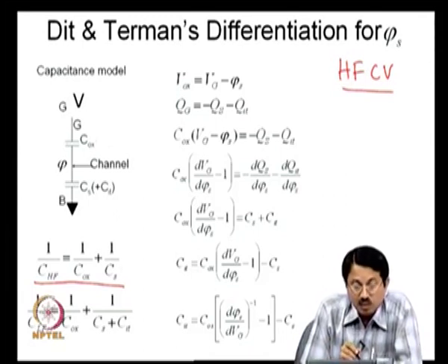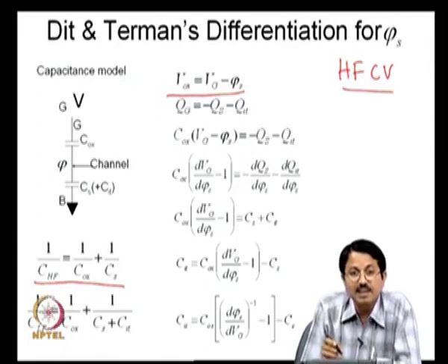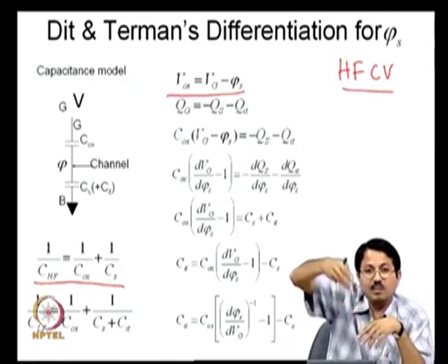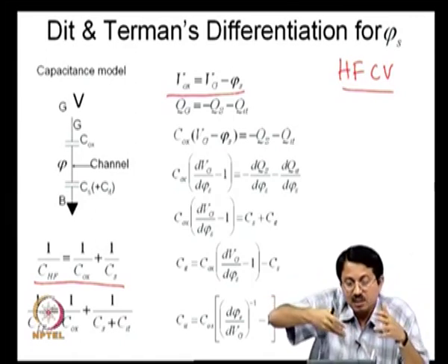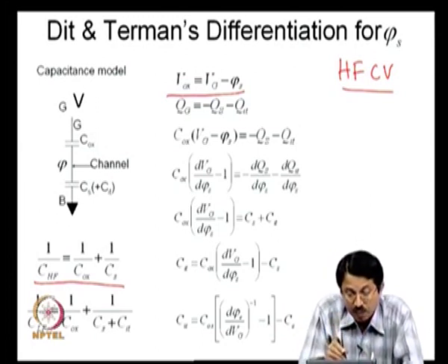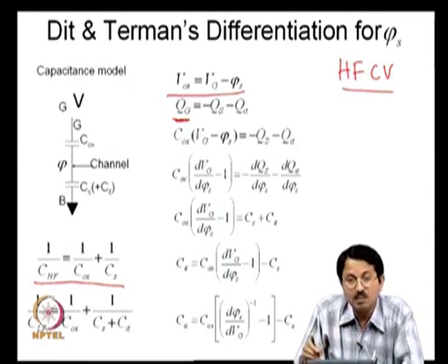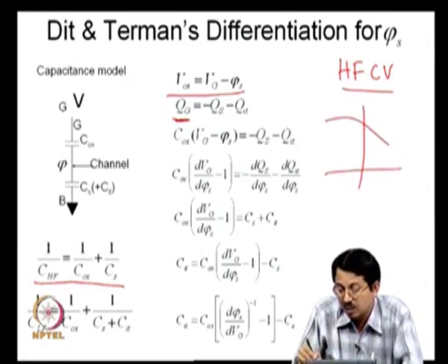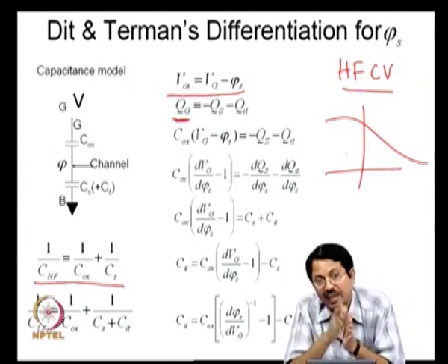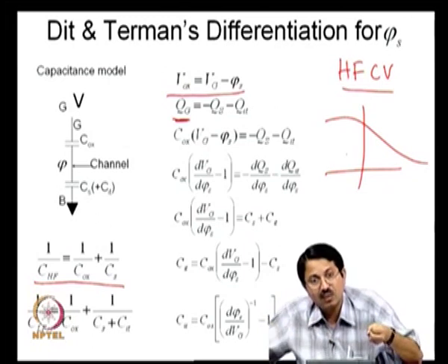Okay. So, let us look at this, right. Your oxide voltage can be written as Vg minus psi s, right, and that is what it is. Vox is equal to Vg minus psi s. Okay. Psi s is a silicon potential. Now, there are two elements in series, total voltage is Vg, subtract the silicon potential, you get the oxide potential. Also Qg, the charge that is put, okay, at any gate bias, remember the stretch out that we are talking about. At any gate bias, when I go from one gate bias to the next gate bias, I give enough time and hence there is a stretch out.